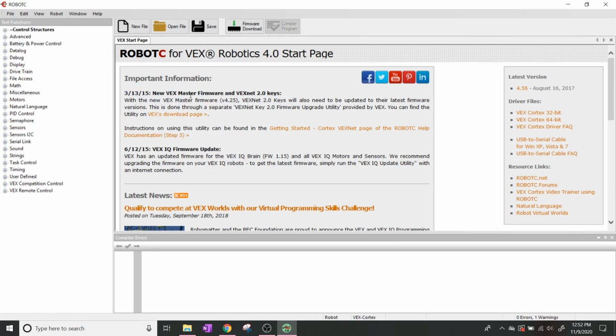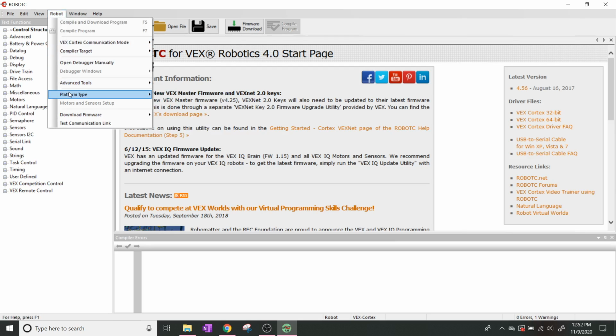So make sure that this is clicked, and you may have to go back up and then click on the next part, Natural Language. Then, wherever it says Vex Robotics, make sure this arrow goes out to the side and that you have it on Vex 2.0 Cortex and not Vex IQ. So we need those three things: Vex 2.0 Cortex, Vex 2.0 Cortex here for Vex Robotics, and Natural Language. This will help us make sure that we've got everything where we need it to be.